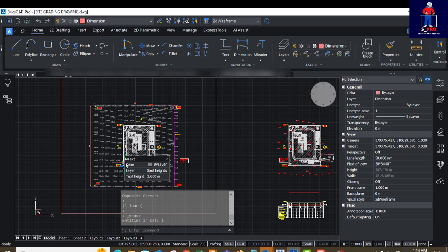Just like I told you, the reason why I raised the site up is because I was told on site that each time it rains, the whole place will be flooded. So it's enough reason for me to raise the site up. Whatever you are using as your design level, you need to have a good reason for it, because the client will ask you, why do you choose to raise this site up? Why not use this? Why not use that? You should be strong in your decision and know that you have a substantial backing for your decision.